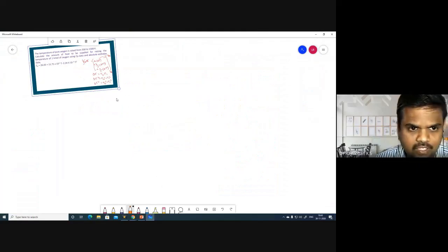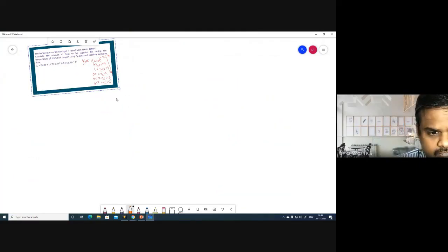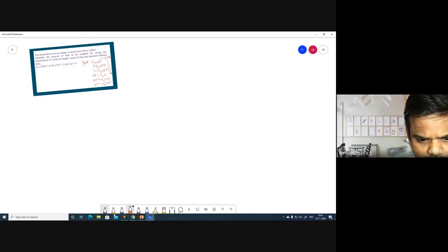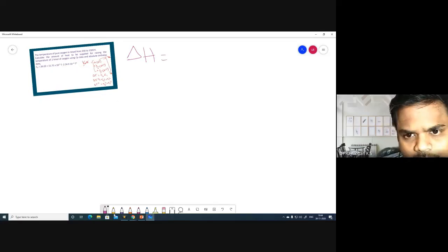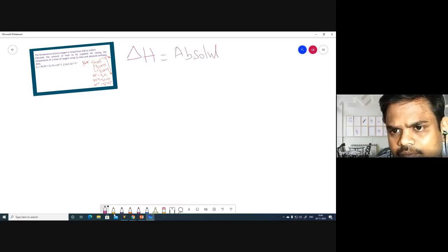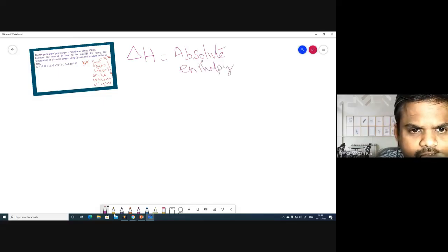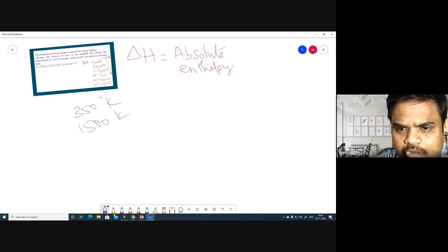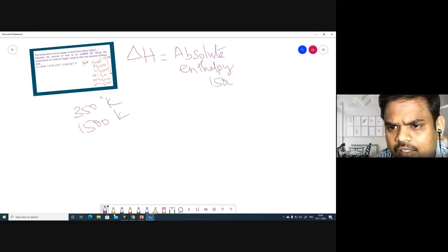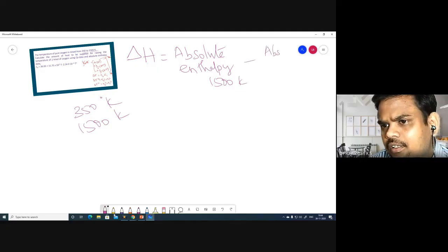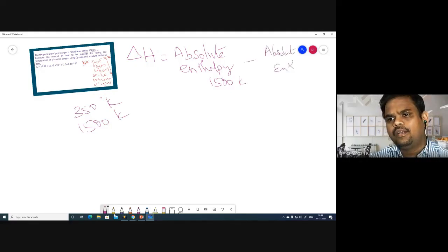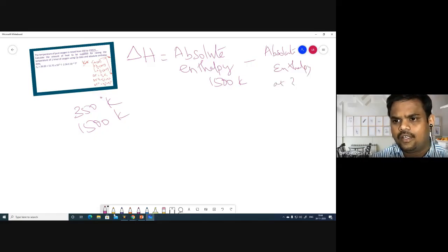So it is given 26.03, right? So what is delta H? Delta H is the absolute enthalpy at 1500 Kelvin minus the absolute enthalpy at 350 Kelvin.